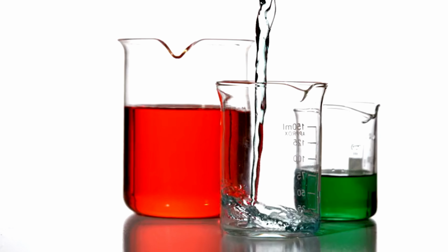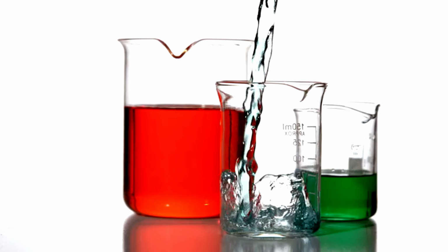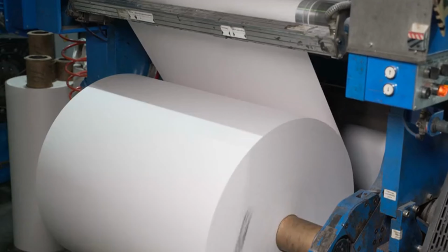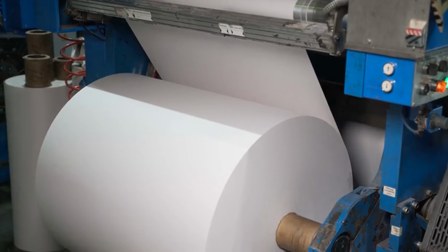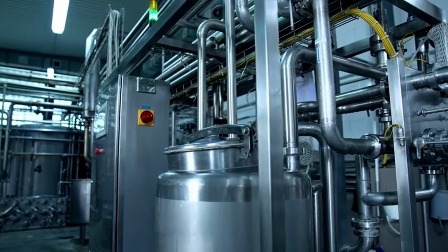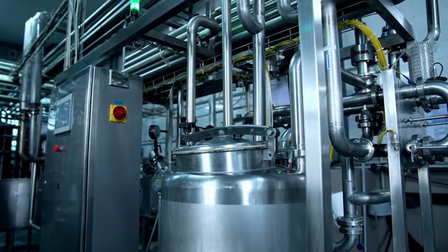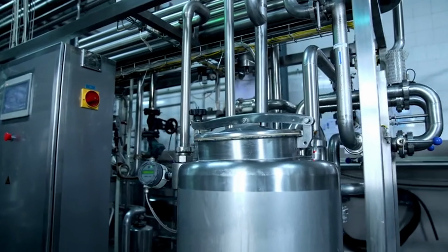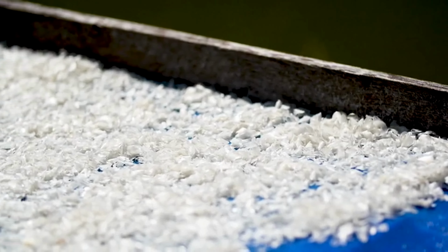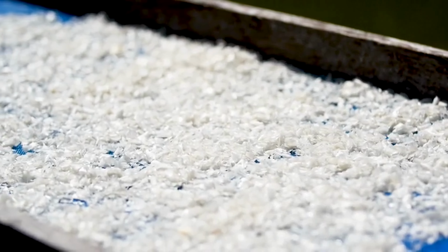B. Chemical pulping. Strong and durable paper. Uses chemicals to dissolve lignin, leaving only cellulose fibers. Produces stronger, higher quality paper, for example, office paper, packaging. Two main processes. Kraft, sulfate, process: most common. Produces brown pulp, can be bleached. Sulfite process: produces whiter pulp, but less common due to environmental issues.